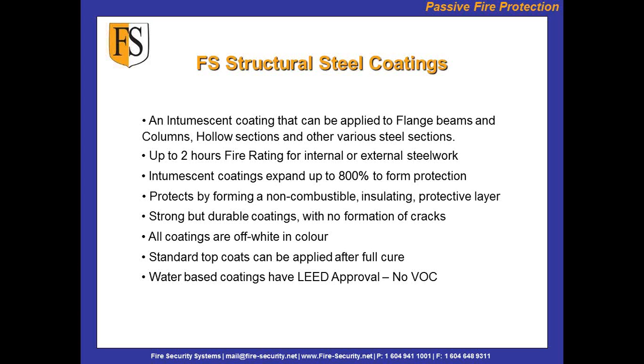And that leads straight to the next point. Standard top coats can be applied after full cure, whether they're latex or acrylics. Externally, we obviously prefer our FS84 top coat over the top of our 370 if it's an external application. But any 100% UV, 100% waterproof urethane, locally manufactured, will do. But we can't guarantee whether that's going to adhere or not. So if anyone wanted a guarantee, it would have to be fully tested first. But we know our FS84 is tested against our product.